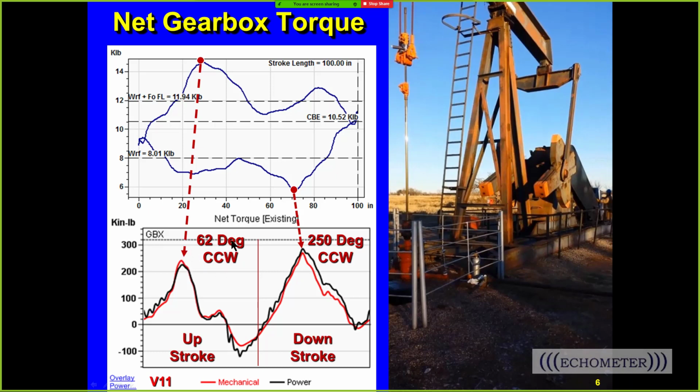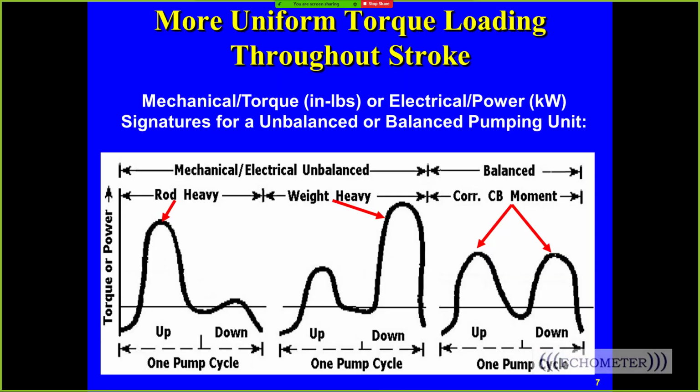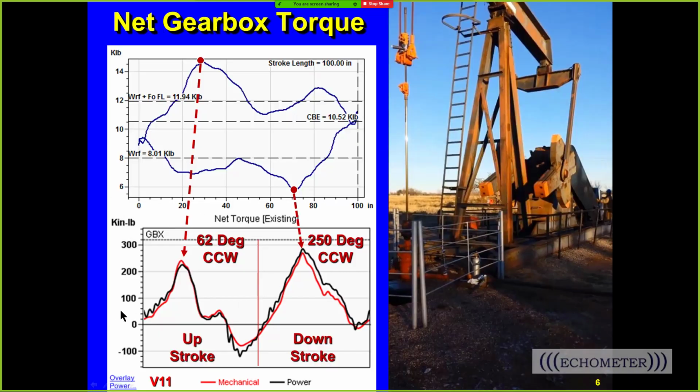So ideally, when you make these two peaks the same, you have the lowest cyclic load factor, and it's the most efficient, and the least amount of energy is being wasted to heating of the motor during changing speed due to cyclic loading. Now, this is a plot of the net torque curve. So this is the net torque curve here, calculated in black and in red.